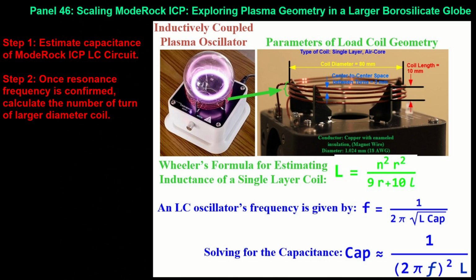Wireless frequency measurements with a Yaesu transceiver provided capacitance estimates, bypassing the protected printed circuit board, or PCB, without direct access. A new load coil of insulated 12-gauge solid copper wire was constructed to match the larger setup.